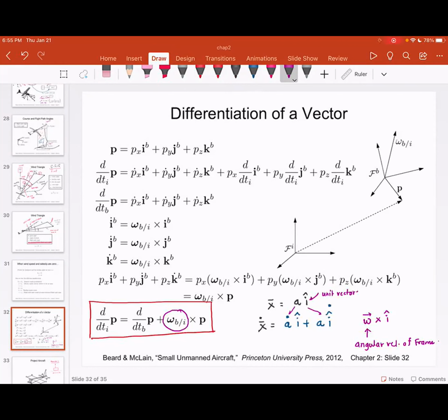And if you recollect, when we looked at the Lagrangian dynamics in the last part of robotics 1, we did something like this. And at that time, I showed you the circle of vectors. I, J, K, and we saw I cross J is K, K cross I is J, J cross K is I. But if you go in the opposite direction, I cross K is minus J, K cross J is minus I, J cross I is minus K. So we looked at this circle of vectors, and that is exactly what this is.